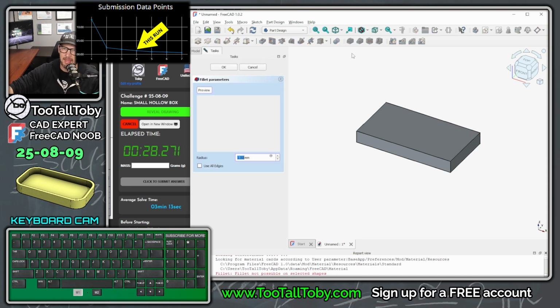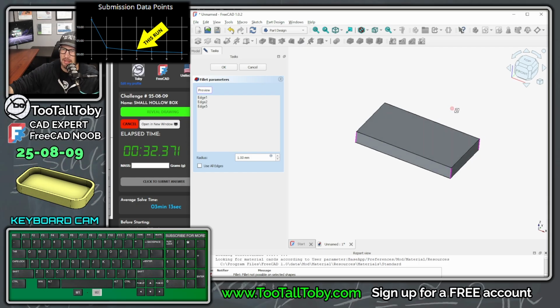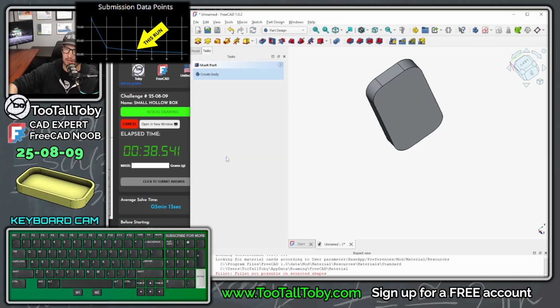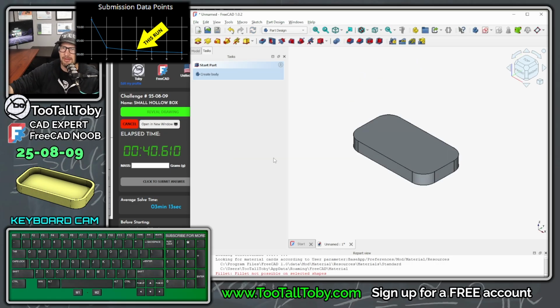And then we're going to launch the fillet command here, and we're going to pick these 1, 2, 3, and 4 edges here. And we're going to assign a radius to those edges of 8, enter, and then we can press 7 to go back to an isometric view.